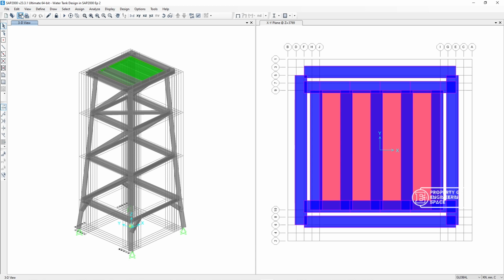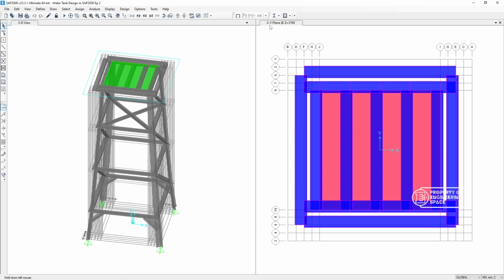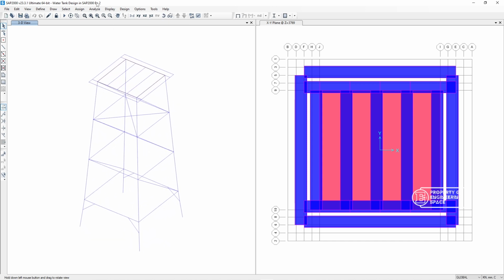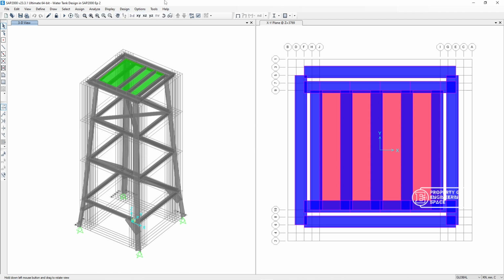So after that, all we need now is to set up, start from the geometry itself, and then after that the plan view from the X and Y translation. And before we hit run analysis, one of the more important things is to set the joint, or to assign the joint on our model.